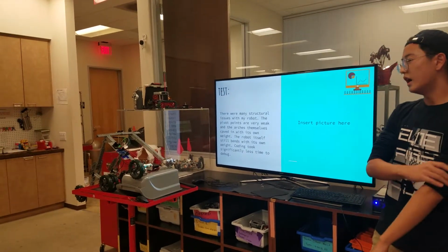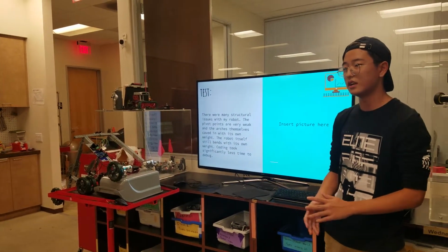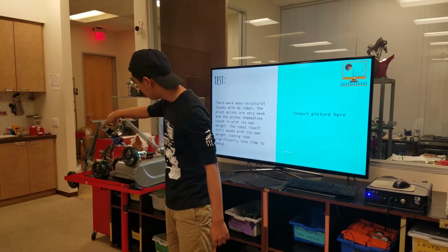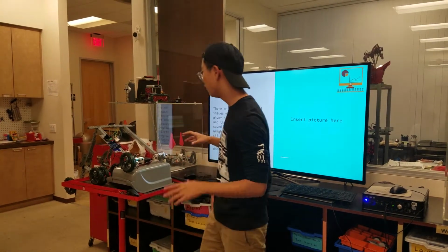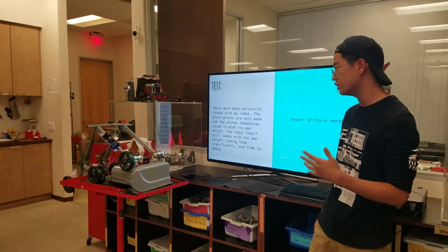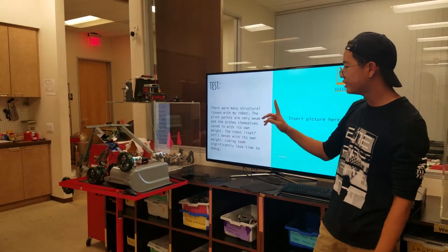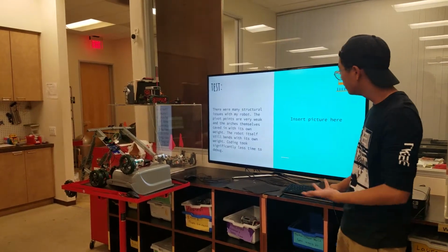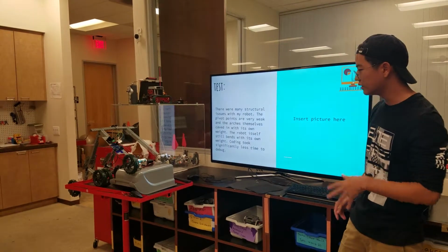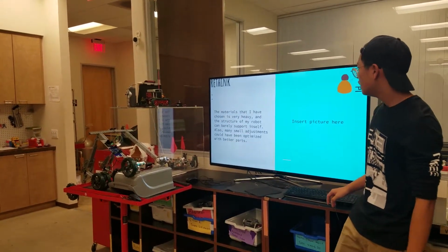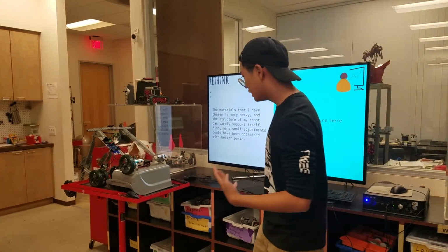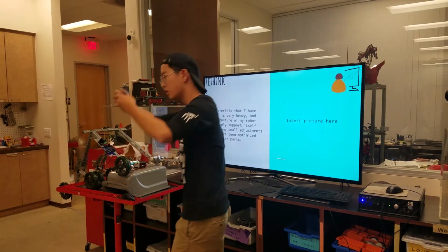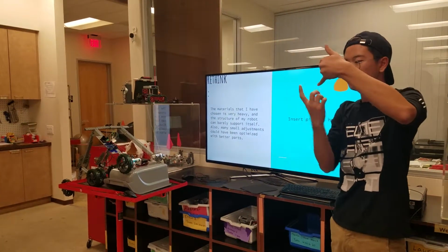And so test. I spent most of my time actually testing the structural integrity of the robot, like with this little bar here. The problem was that the arches themselves were collapsing on themselves because of the material I used, which is steel. So it's very heavy, and my structure couldn't handle the stress, so I had to add a lot of arches and rethink some designs here and there. When I rethought this, I added arch plates through here, and another plate here, so it has a dual plate, so I can hold the pivot points better in place.